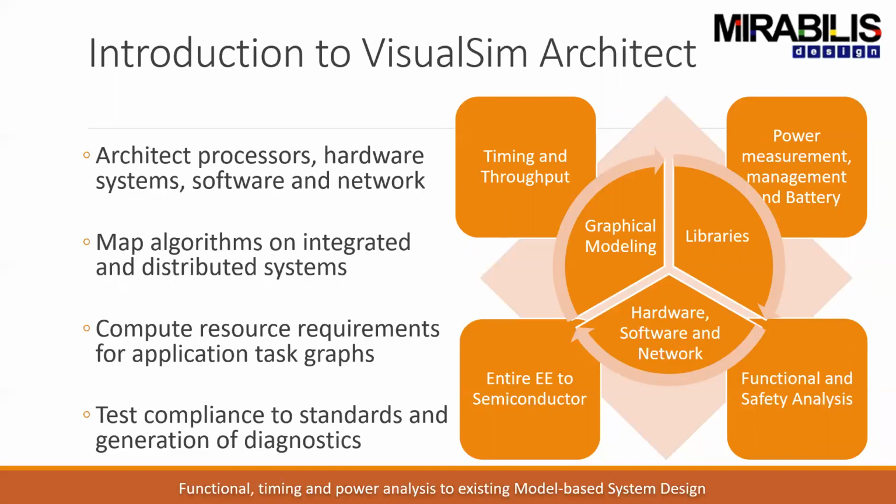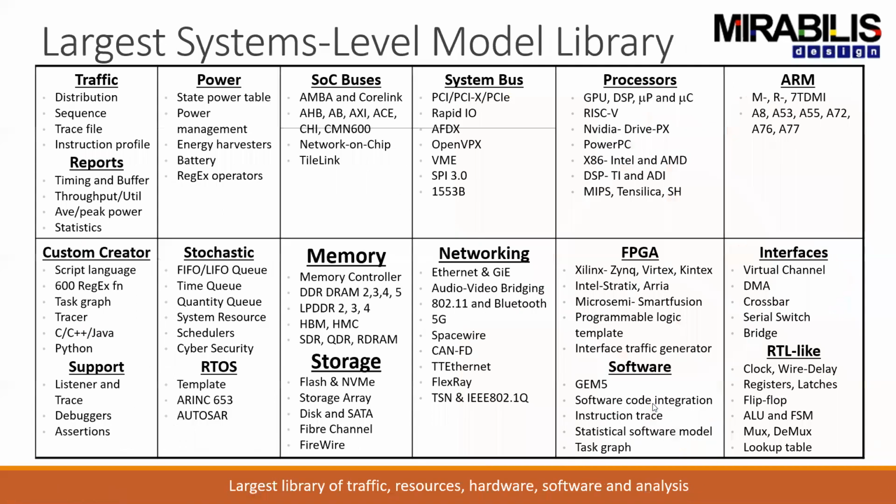One of the key things that we do with VisualSim is look at functional safety. How does a particular design work in the context of a full architecture? Meaning that if I have a failure in one part of the system, does my system still continue to operate, or is it not going to work at all, or is it going to work but not meet the requirements? Being able to evaluate those very quickly is an important part of the exploration that you do, and that's where VisualSim provides you the functional and safety analysis.